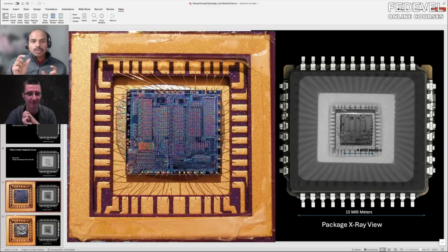Yes. On top of JTAG, we also have additional structures. Fundamentally, JTAG helps if, first of all, there is some manufacturing defect, say a bond wire is broken. In those cases, it's fundamentally not a good silicon, so JTAG may not be of good help. But similar to JTAG, we do have what we call a scan-in. Some of those structures.